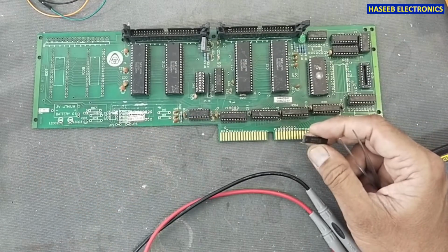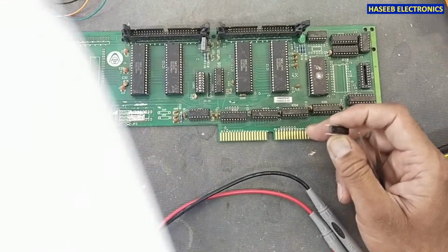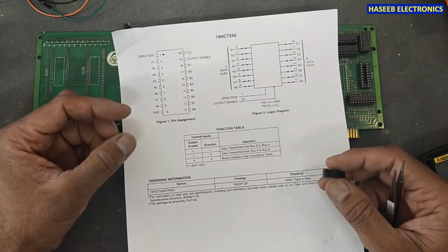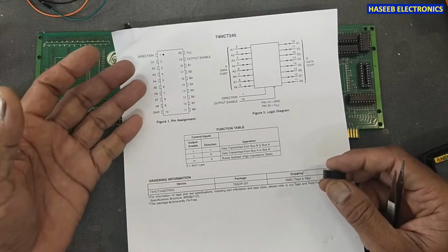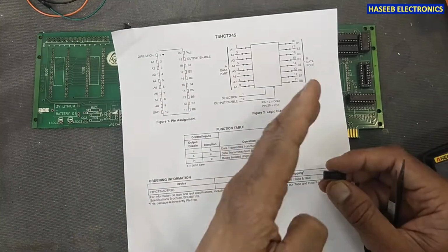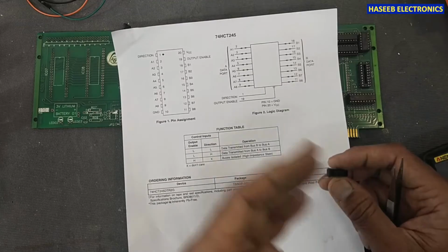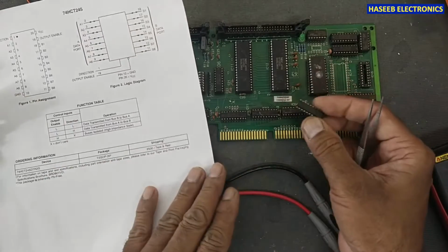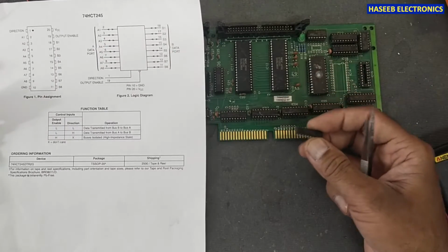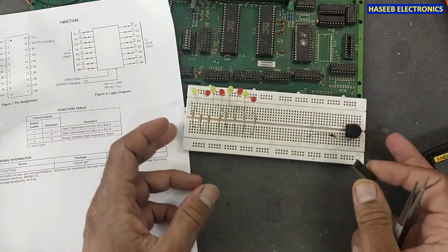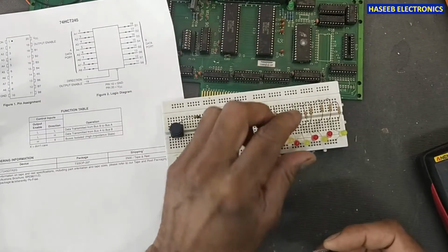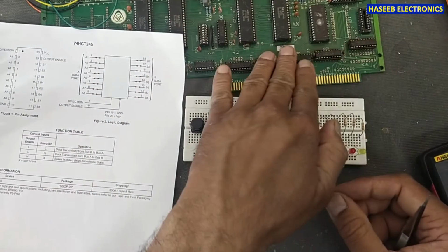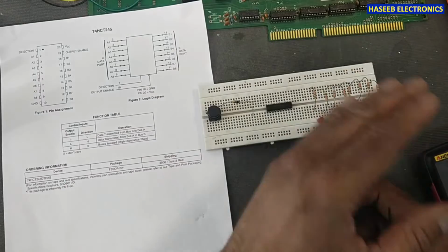Transceiver, basically, is a line driver. When the processor is working, the processor doesn't have too much current to communicate with many devices, because every component has sink current. For that purpose, these drivers work as a signal booster. To test this IC, I will use these LEDs to display the signal. When we have many ICs on the same line, if one IC is bad, all the data will be interrupted.